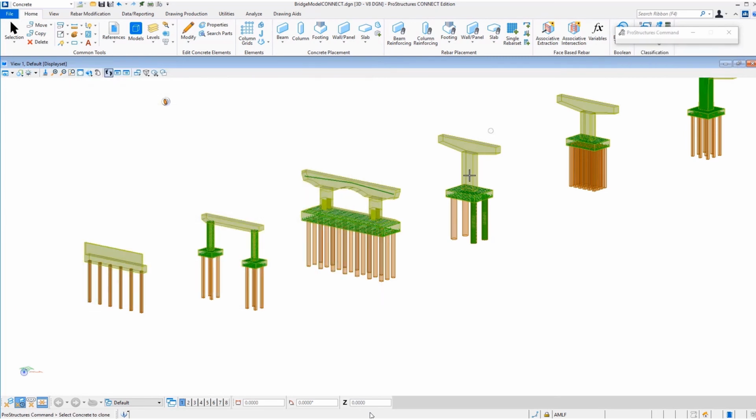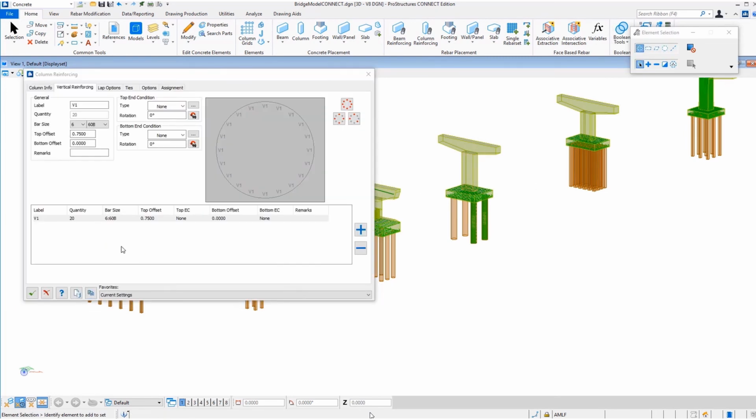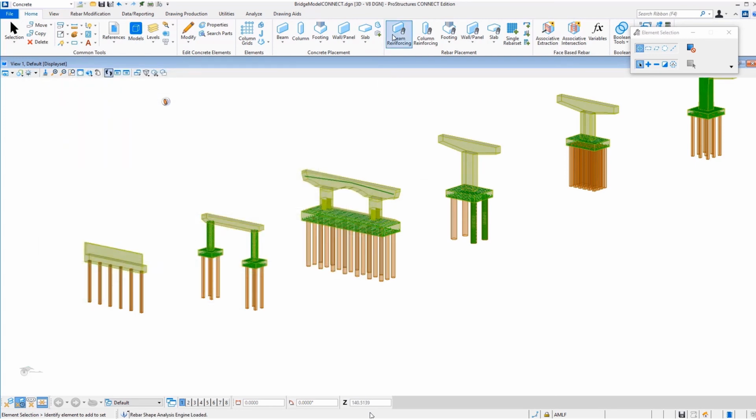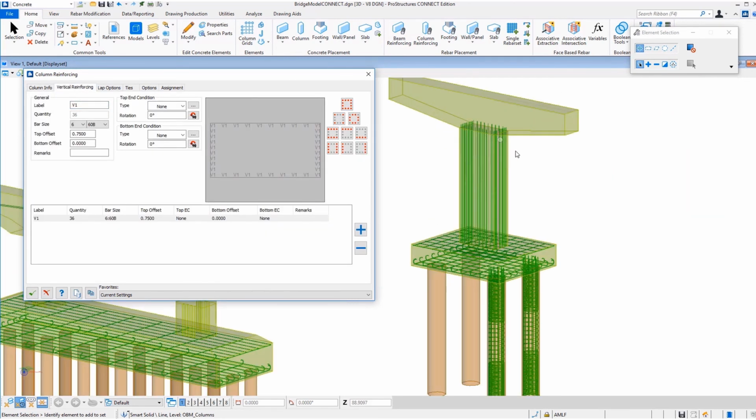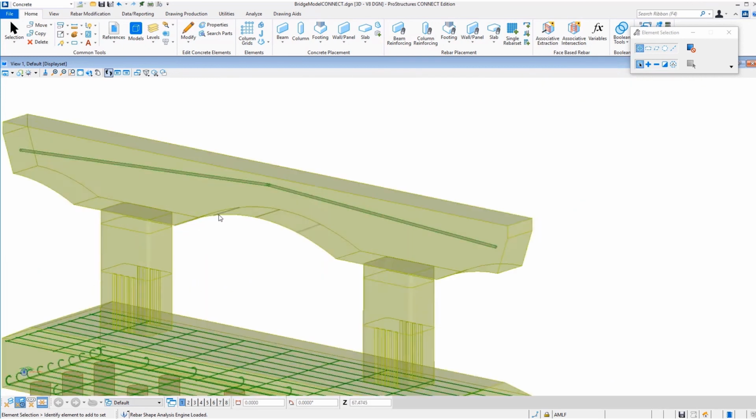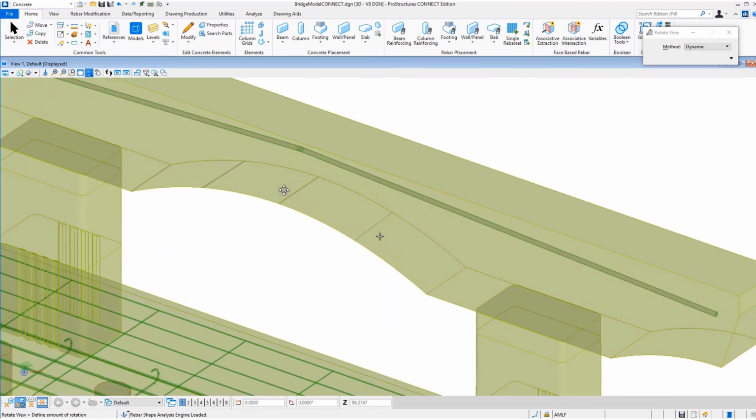So these are, for example, predefined elements. A square column, a cylindrical column. All of that is fairly easy to annotate in full 3D, right? Here it is just a matter of selecting the structure and the bar arrangement that you want. And this is shop drawing detail level, right? So there is nothing schematic on that. This is really using the rebar, the lap lengths that it needs, the dowel lengths, the hooks that it needs, the pin radius that you need to bend each hook, and all of that. So this is something that you can also take advantage of if you get the model right.